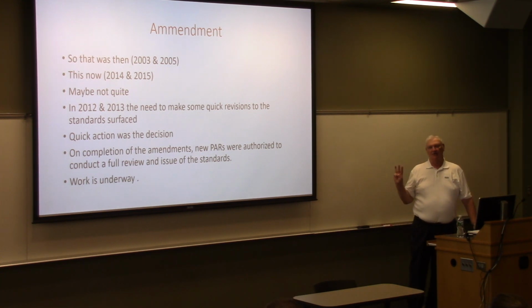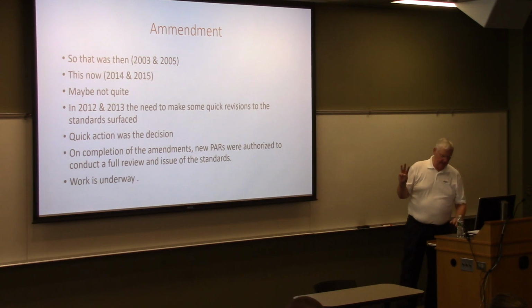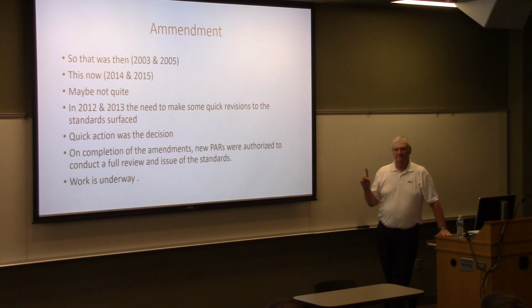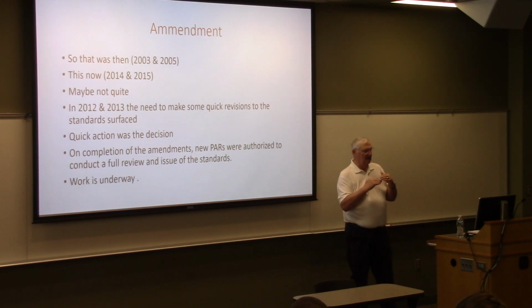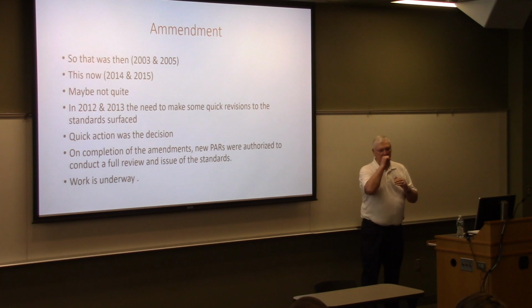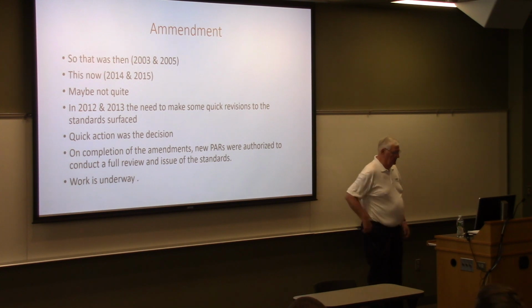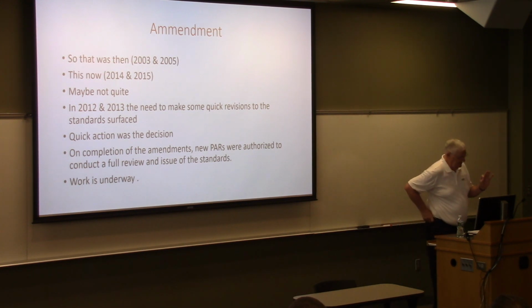Now, we amended the standard in three cases. One is it was now permissible, not only permissible, but desirable for a distributed energy resource to contribute to voltage regulation at the point of usage, not so much by actively regulating, but by providing VARs into the system to compensate for excessive VAR draw where it is located in the distribution system. And this sounds great. I mean, as far as the utility operator is concerned, it's a really good thing.